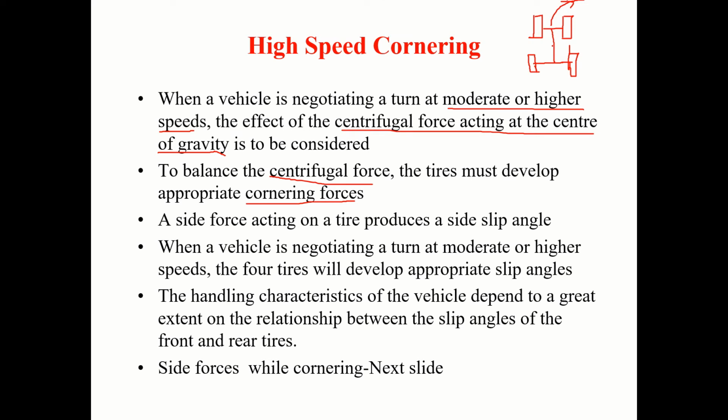Then the centrifugal force will be acting this way. So to resist these centrifugal forces, you will get these forces over here, right? Those lateral forces. So to balance the centrifugal force, the tire must develop appropriate cornering forces. These are cornering forces.